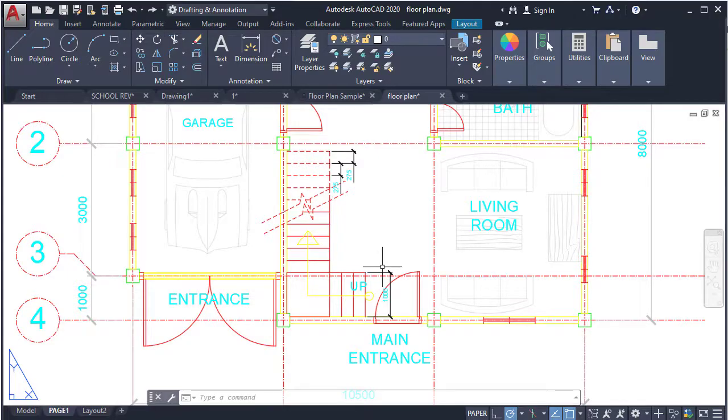This is now the problem of using a standard dimension style, because of the visibility of the 1:100 dimension style and at the same time the 1:50 dimension style. This can be negated by using two different drawings, but it also generates the problem of having to make two edits when it is necessary. To overcome that problem, we can use annotative scaling.